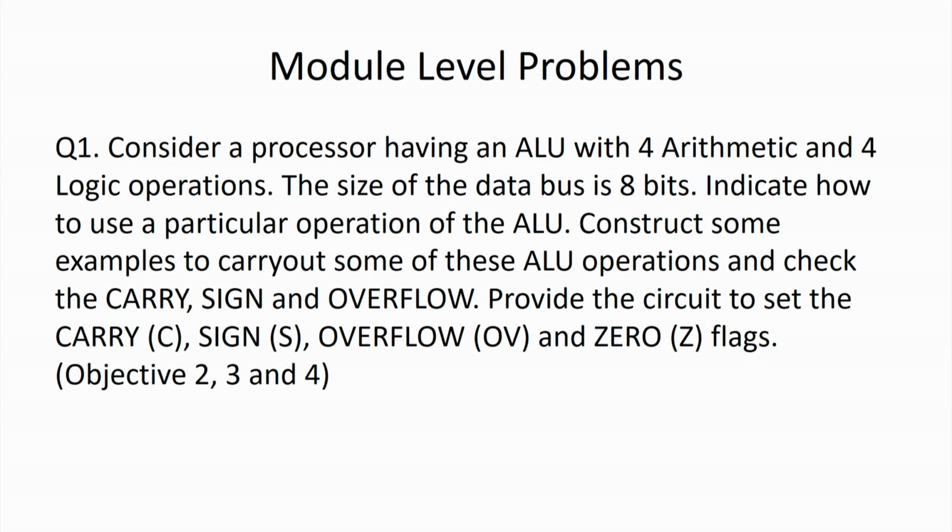examples to carry out some of these ALU operations and check the carry, sign and overflow bits, because you can perform some arithmetic operation and then see the result. In the result, you can see whether it is generating a carry, what the sign is, whether it is positive or negative, or whether it is an overflow condition. So, you just formulate some examples and try to carry them out.